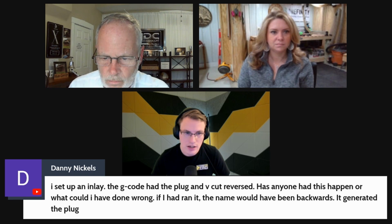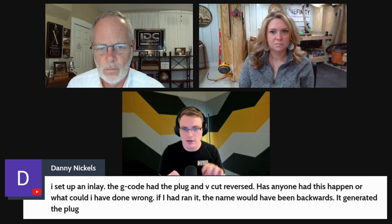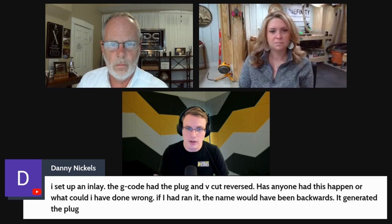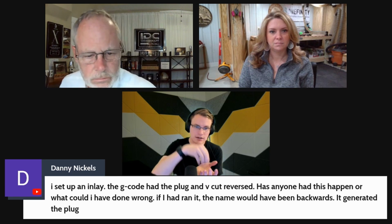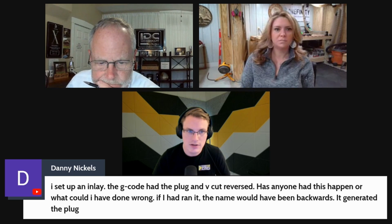It generated the plug. Yes, so it is normal that the plug is mirrored, because the way the V-carve inlay works is the pocket side, which is the female side, will be cut normally, and then the plug side will be mirrored automatically and cut in reverse. That way, when you glue it, the part flips over and glues in the correct way. So yes, it is normal for that to be reversed.